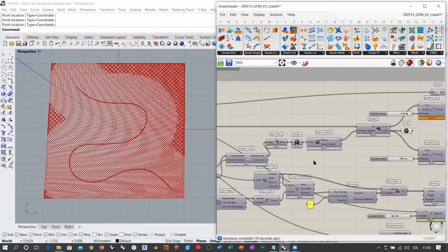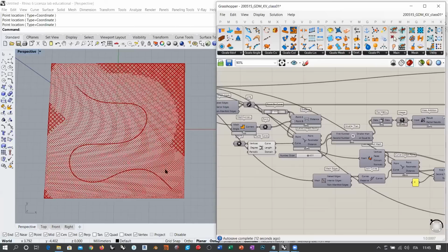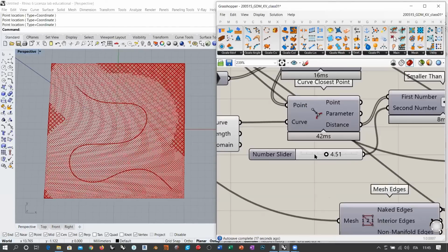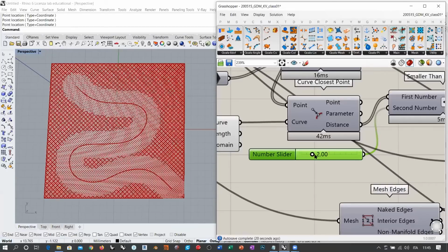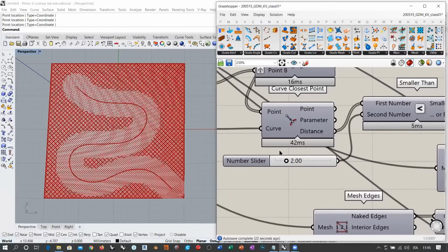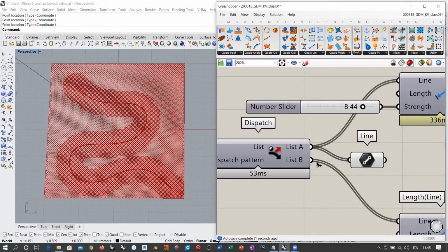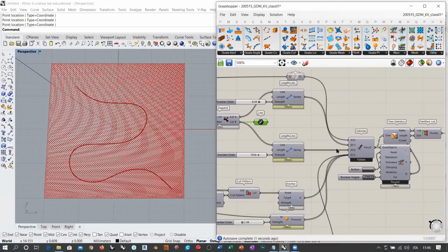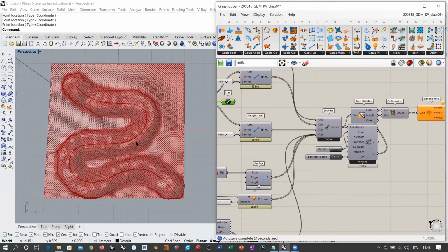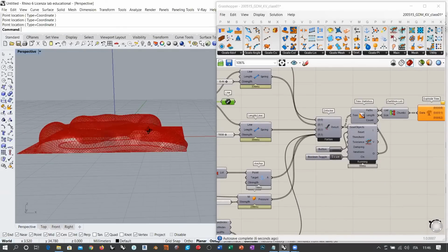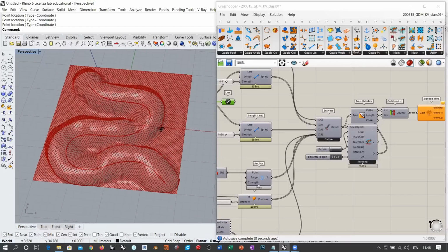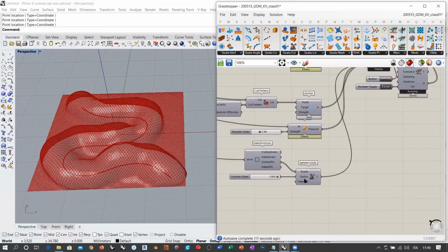Okay, so in this case, as this attractor is occupying most of the extension of my mesh, I'm going to reduce the distance to something like 2. Okay, so we have rigidity programmed, which corresponds to all this set of edges, and the elastic part is going to be this one. This is going to be a little more interesting because the deformation is going to happen along a path, and this is going to be driven by pressure, also with some self-collision.